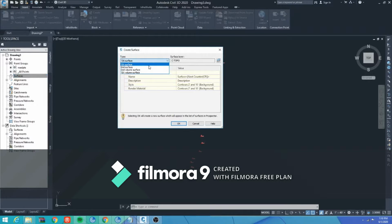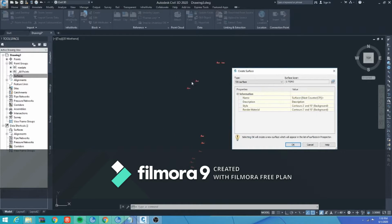I'm going to keep it as TIN surface, and what TIN means is triangulated irregular network. TINs create triangular surfaces, and the advantage of using TIN is that they map out highly variable surfaces such as streams, roads, and lakes, as well as examining localized areas from large-scale maps. Meanwhile, grid surfaces comprise points that lie on a regular grid, and they're typically used for examining large study areas and for mapping more uniform surfaces.